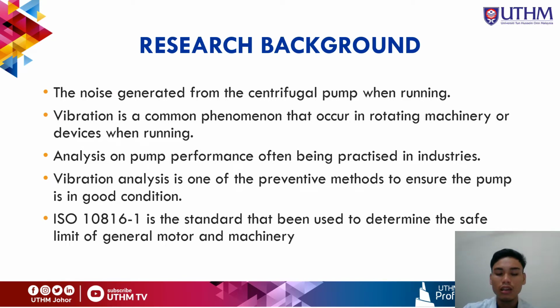The analysis of pump performance is often practiced in industry. This analysis is often used as a preventive method to ensure the pump is in good condition without stopping the operation of the pump. This research also uses ISO 10816-1 as the standard to determine the safe limit of general motors and machinery.